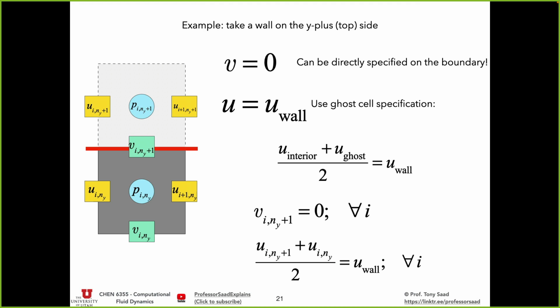All right, so now let's take the y plus and repeat the same procedure. I'm trying to explain to you the process so that you can reason about it on your own. Most of the time we're giving you all of that. If it's a stationary wall, it will be U and V equals 0. If it's a moving wall, I will give you the tangential component, right? If it's an inlet, then the normal component would be non-zero. But then you calculate the ghost cell on the component where you don't have a degree of freedom, right?